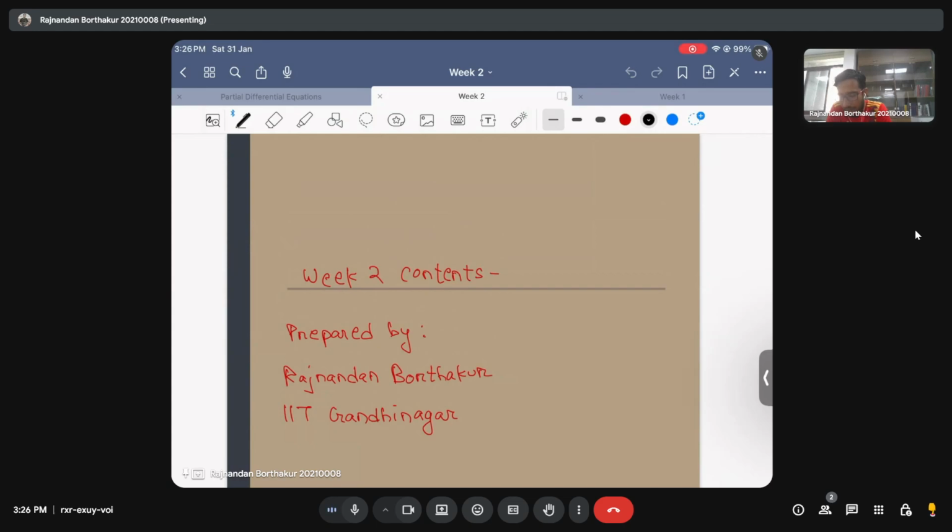The first, and I would say a very simple case, is something that you have already seen through the lecture series videos of this week, known as the unidirectional rectilinear flows. For instance, the x directional velocity profile, if you have a flow known as the Couette flow, where the upper plate was moving with some velocity and the lower plate was stationary, which actuates the flow in between these two plates.